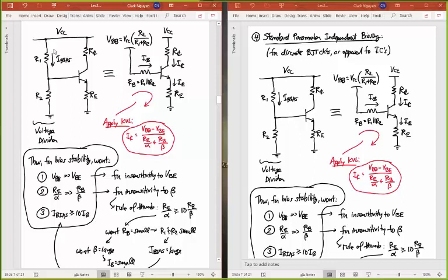And if you have a voltage VCC that's on the order of 12 volts or some large voltage there, then you need a large resistance to get that current to be very small. Okay, and so, you know, resistance is I guess off chip you don't care that much about resistance size, but when you go on chip you're going to care a lot because resistance takes a lot of space, and space means money when you're on chip.